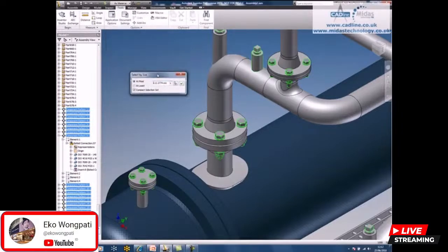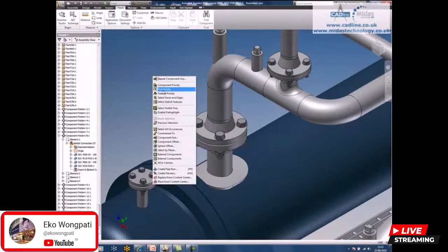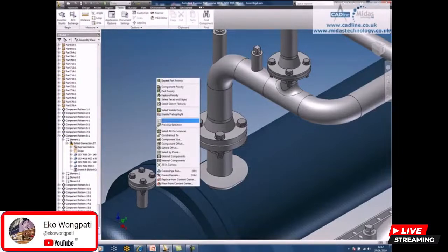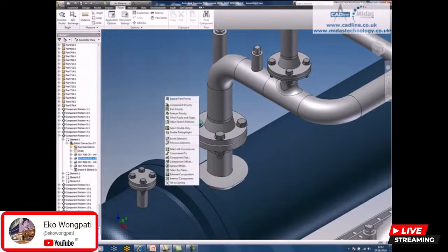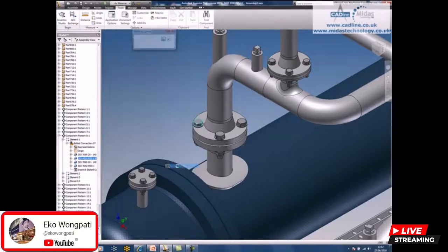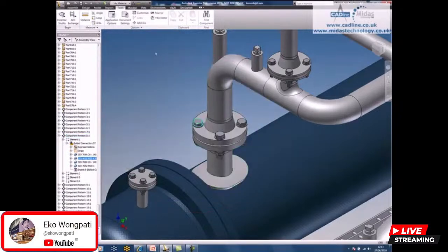So you can see within the dialog box we've got choices as to whether you want at least or most. It specifies a size there, which you could type in a slightly smaller or larger one if needed, and then move on from there. Keep in mind that there are quite a few of these to use. Again, with part priority, you might pick this, and I might also come back over here and say that I'd like to do a sphere offset on this. You can see that everything completely bounded inside of the sphere can be picked, which can really speed things up quite nicely.